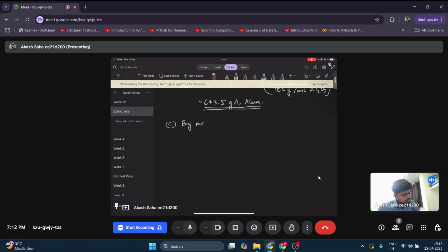By mass balance, the concentration of stock solution times the discharge of feed will be the concentration of the process times the discharge of the process. In that way, we can find out the feed rate.